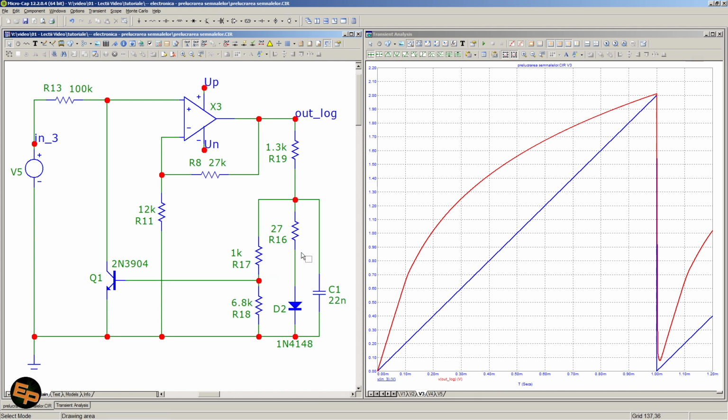So I've chosen to have a bit of extra voltage, and in order to do that, I have placed a smaller resistor in series with the diode, so that it has an extra voltage drop, so that overall the voltage drop on both of these components is slightly higher than the voltage for a transistor to open, and therefore we can play a bit with how fast or how slow we are turning on this transistor.